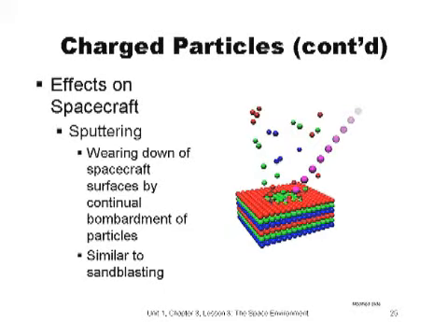Charged particles hitting a spacecraft's surface can also cause sputtering, which you can think of as molecular sandblasting. The continual bombardment of surfaces by molecules can eat away at surfaces over time. Usually, sputtering is not a problem unless spacecraft are in orbit for 30 years or more.